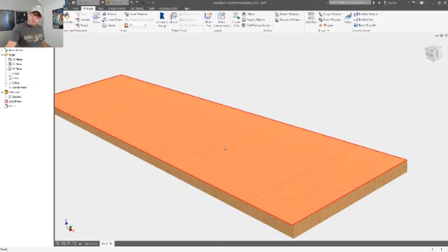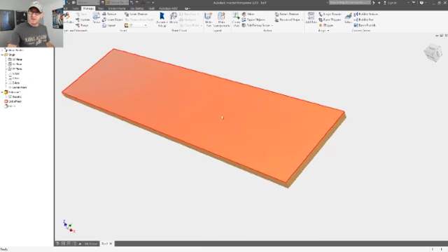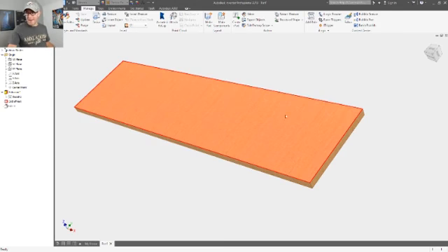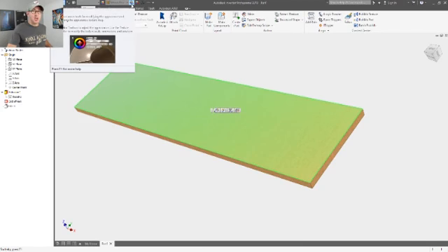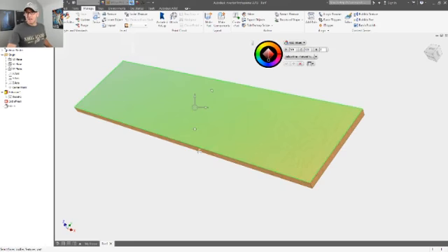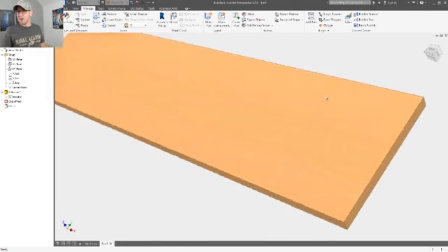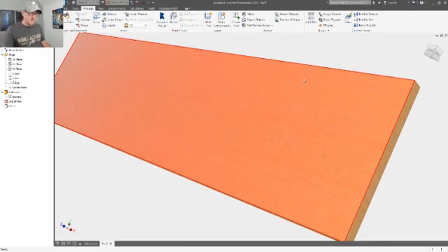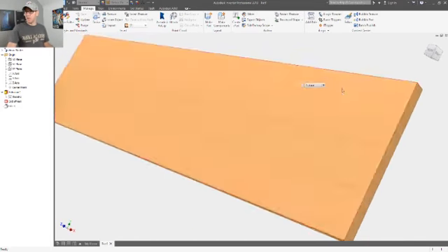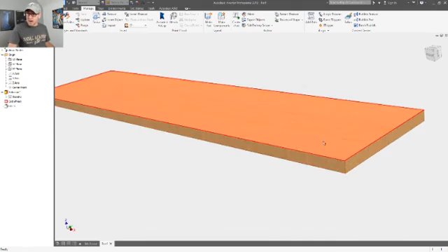And what I can do is pick that specific face, right there, and I want to orient that grain so it's going 90 degrees to where it is right now. I'll pick that face. I will go to my adjust option, and inside the adjust option, you grab this lower grip here, and you're going to rotate that 90 degrees, and now you have to hit the checkbox. Now I can see that I rotated that, and now my grain is traveling the direction that I want it to travel. You can see this grain is incorrect.